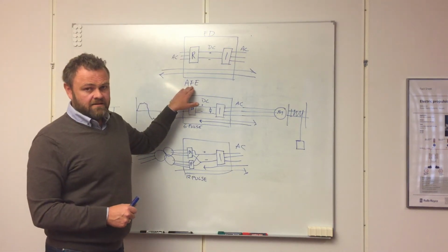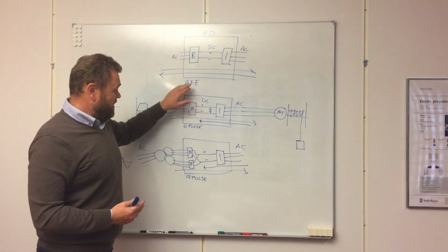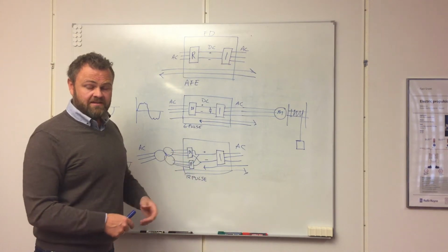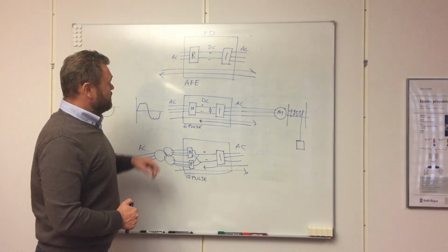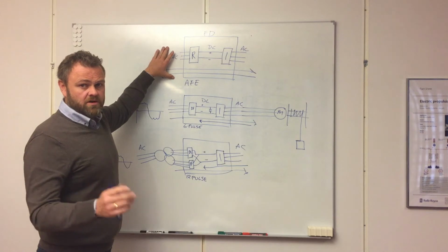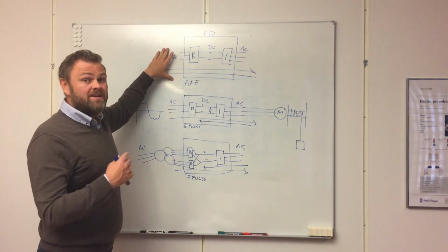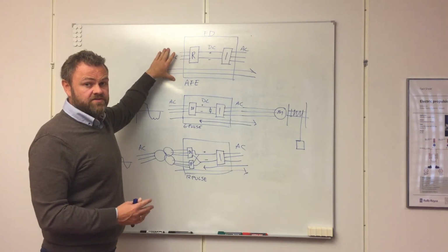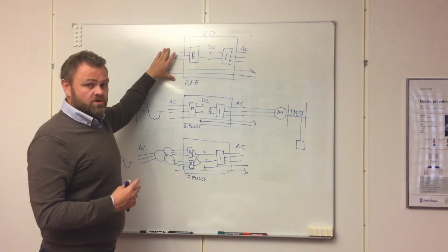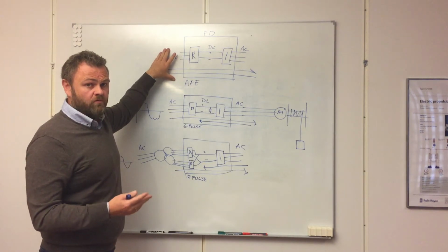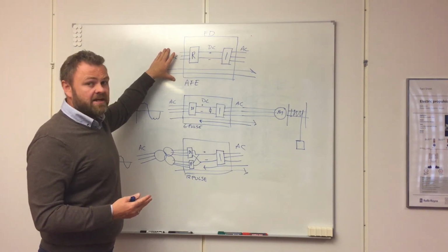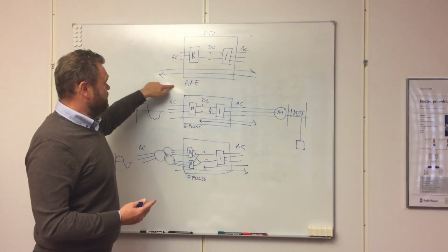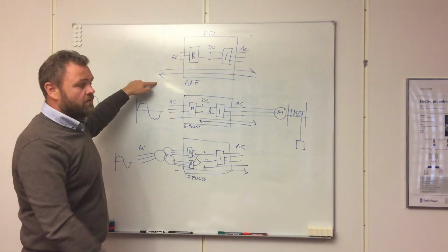With the AFE that we have standardized on, we have 6 pulse and 12 pulse in our portfolio. We can deliver that as well. But due to our long experience with more than 200 vessels now sailing with megawatt frequency drives, we have gained so much experience, and we know exactly how we brake the energy coming back from the propeller, from the winch, from whatever is out there.